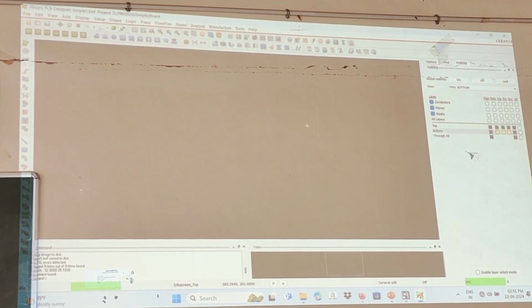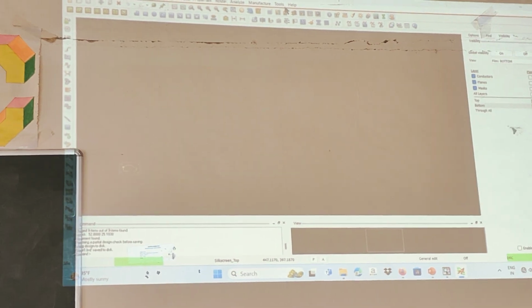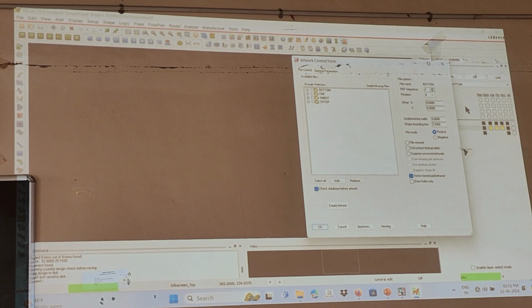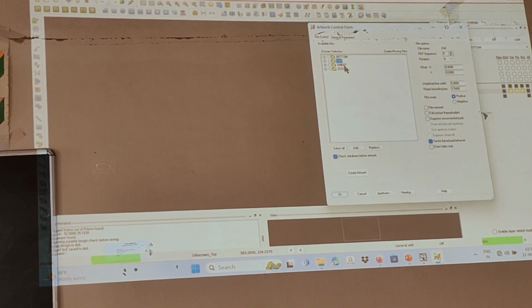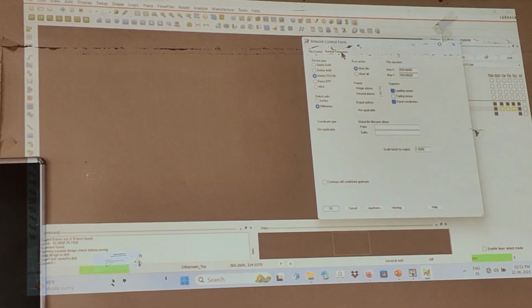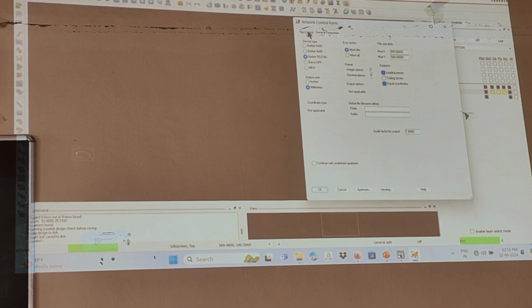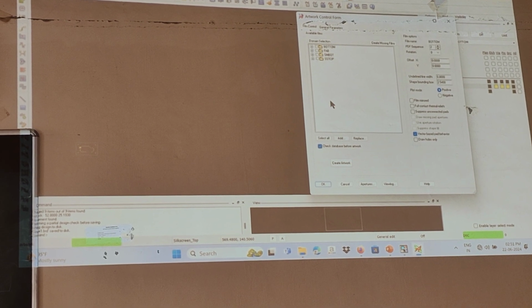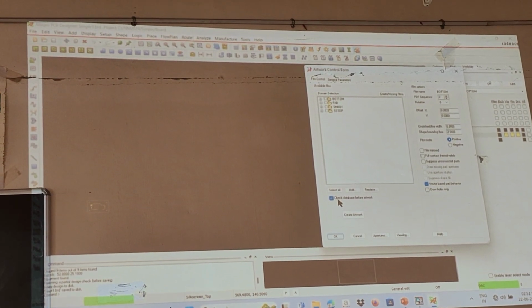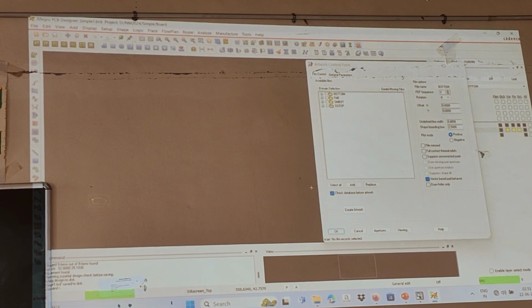Now I am going to create the Gerber file. Go to manufacture, artwork, and check once again whether the information we gave before is correct and available now also. Then go to film control and check database before artwork, and then click create artwork, give yes.